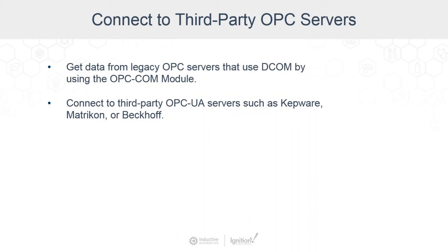Anytime you're dealing with a lot of EFM data, at least in the oil and gas industry, there are some specialized communication rules that have to happen. So we've used Kepware quite a bit in our large-scale implementations. Being able to even write drivers for the Inductive Automation OPC server has helped us integrate with other applications that don't have a readily available communication path. So OPC is really what's empowering a lot of our ability to collect this data for our clients.